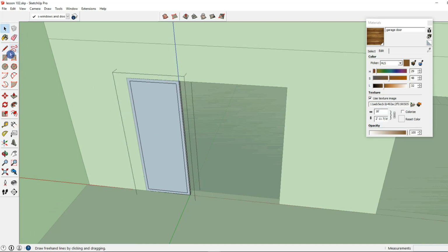And there's a couple ways we can do that. One, because it's going to be an even number of divisions, I can simply click on this midpoint and drag, and it automatically breaks this line. And I could click on another midpoint there, another midpoint there. But there's another way I can do this, is just clicking on it, and I could hit divide, and there I could change, right now it's set to 7 segments. I could change it to 4 segments, and now it will be divided into 4 segments. So now you can see there's an endpoint, endpoint, endpoint. It would also create midpoints in between those as well.